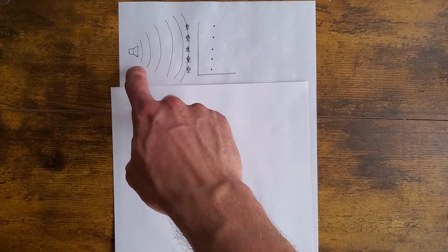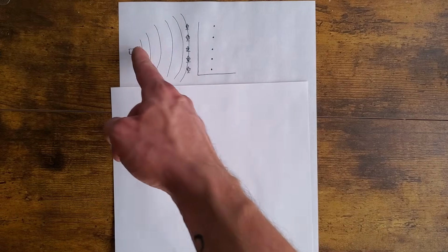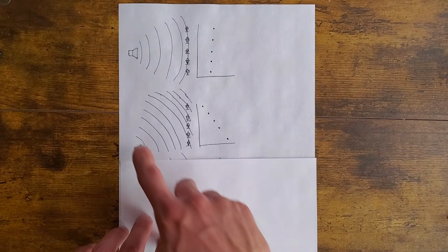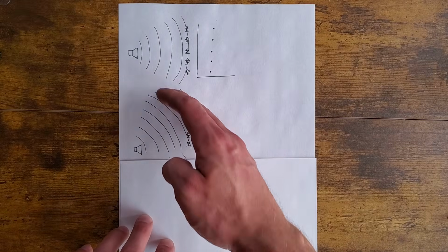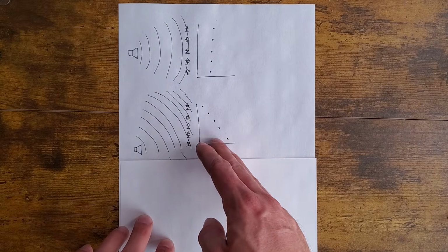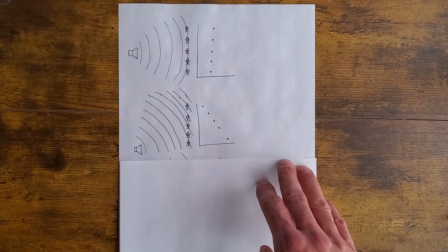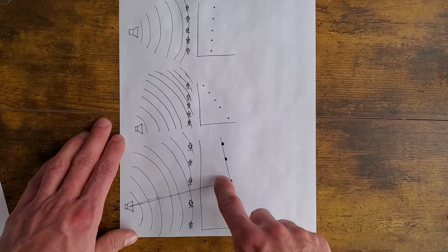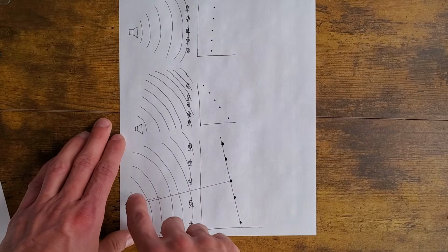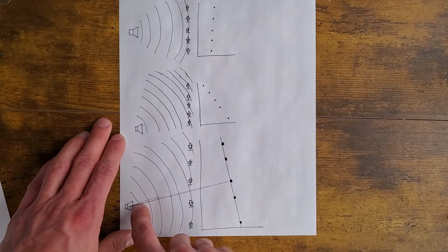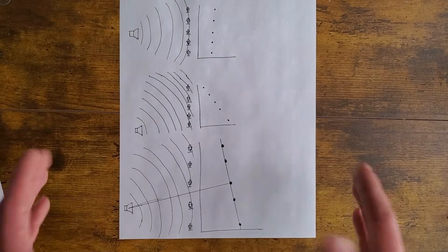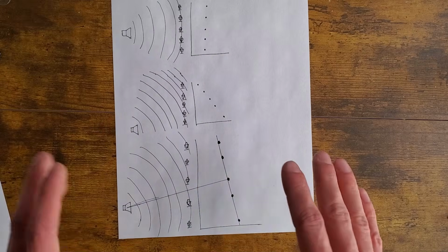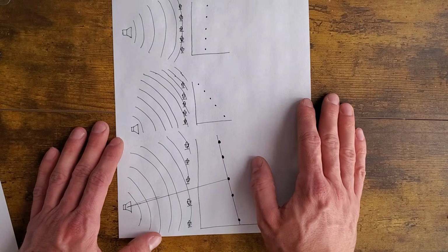If the sound is coming from straight in front, then the sound hits all these microphones at the same time and the graph looks like this. If it's coming from down here, then it hits this microphone first and then up, and so the graph looks like this. You might be able to see where this is going. If we just draw a line between all of these different points, and then draw another line at a right angle to that line, boom, that points to the direction the sound is coming from. This seems overly simplistic, but if you do the math to make this rigorous, this is exactly the equations we actually use for beamforming.